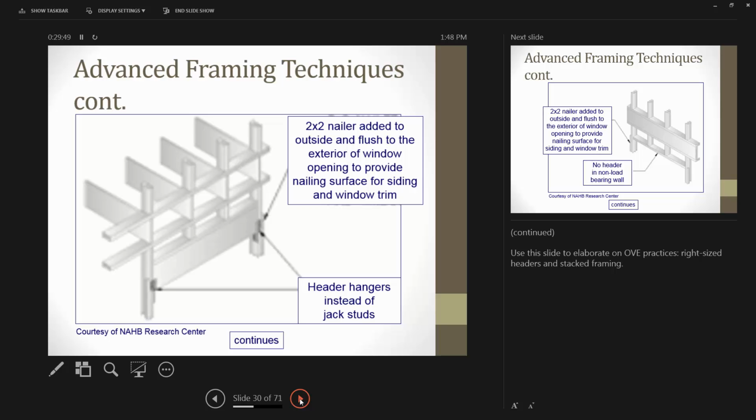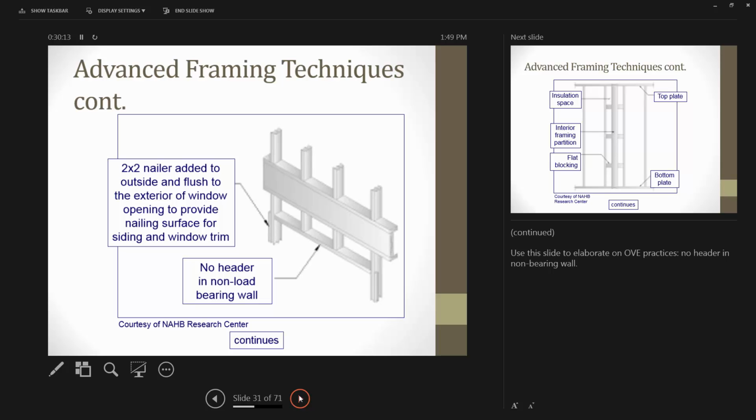That's what they call the top plate, right? Top plate, yeah. You can toenail in your joists, or your ceiling joists, once you're setting your frame. Right, and going back to keeping everything on layout, if your ceiling joist hits right over top of your single wall stud, right over top of your second wall stud, you're just reducing the amount of lumber. And when advanced framing first kicked off, it was a little bit more of the saved lumber